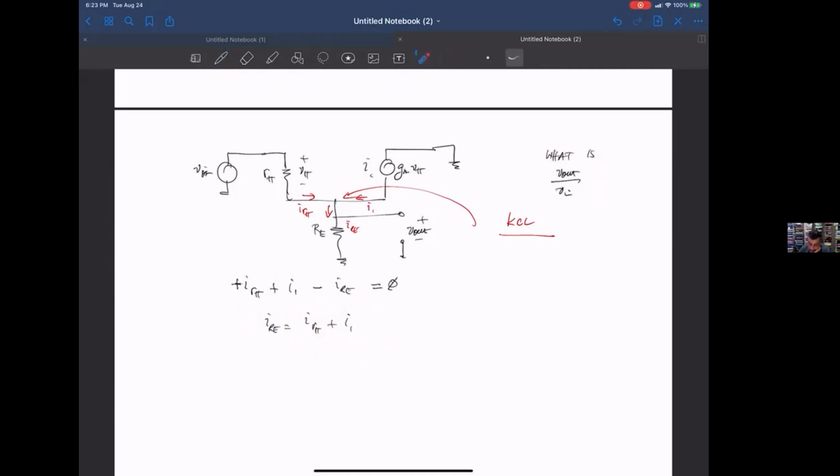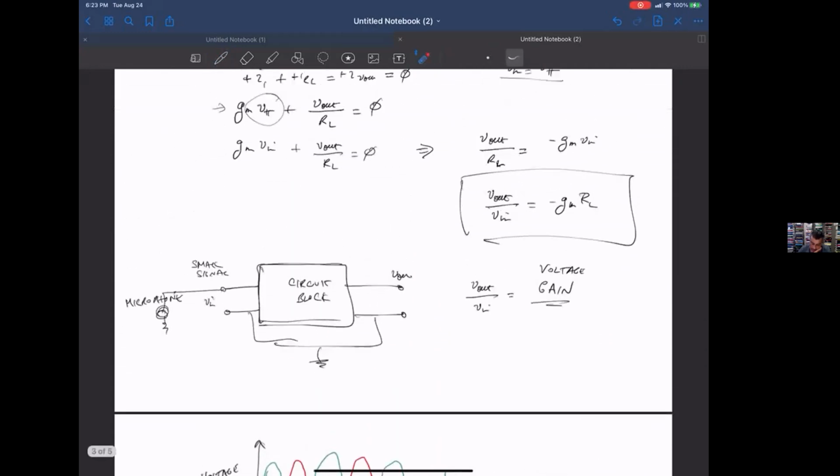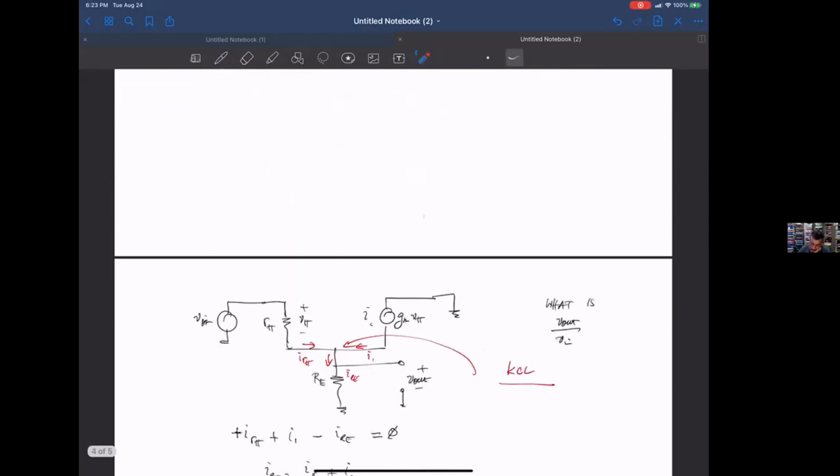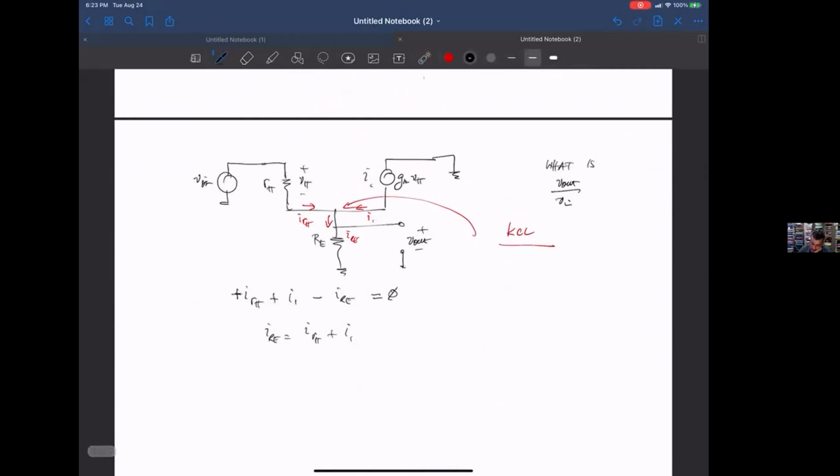The very tempting thing to do here is to say, oh, I remember this V sub pi from the last problem. This V sub pi from the last problem was just Vin. This is a very tempting thing to do, but it's incorrect. You'd say I of R pi is V sub pi over R sub pi. That one's correct. But then saying that's equal to Vin over R sub pi is incorrect.